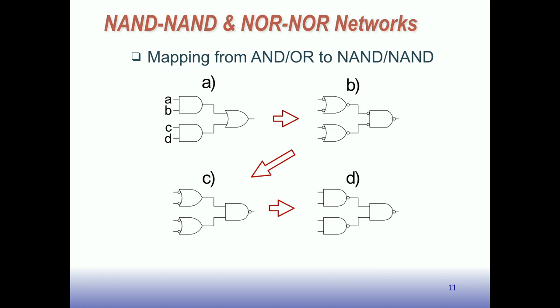By symmetry then, OR-AND, which is product of sums, is going to be NOR-NOR. Right. Now, as we will see later, NOR is not as nice in CMOS as NAND is traditionally. It's getting better all the time, but it's not as good as NAND. NAND is, for the area, the strongest gate for a given amount of area.